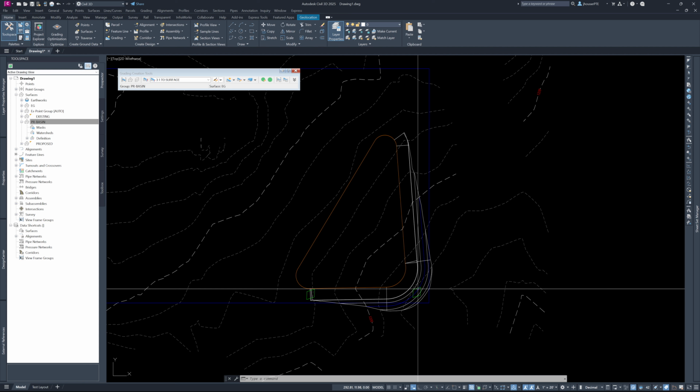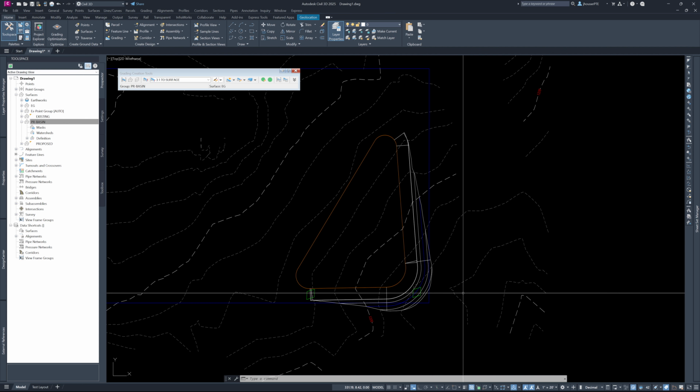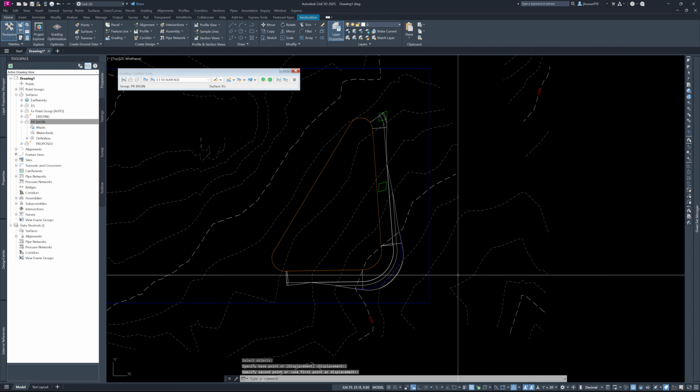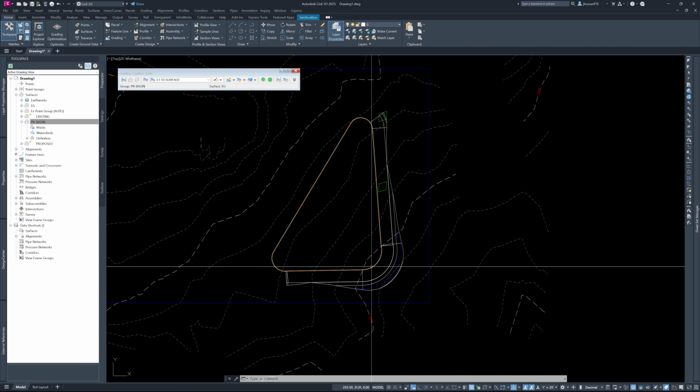Now, obviously, we are way too close to the contours, or to the property lines, so we need to move our base feature line. If we move that, you'll notice our grading objects are all linked to it, it also moves the grading objects, and it recalculates our surface, our contours, and how it would tie in. So again, we can just select move, just kind of slide those around, and our grading will change.